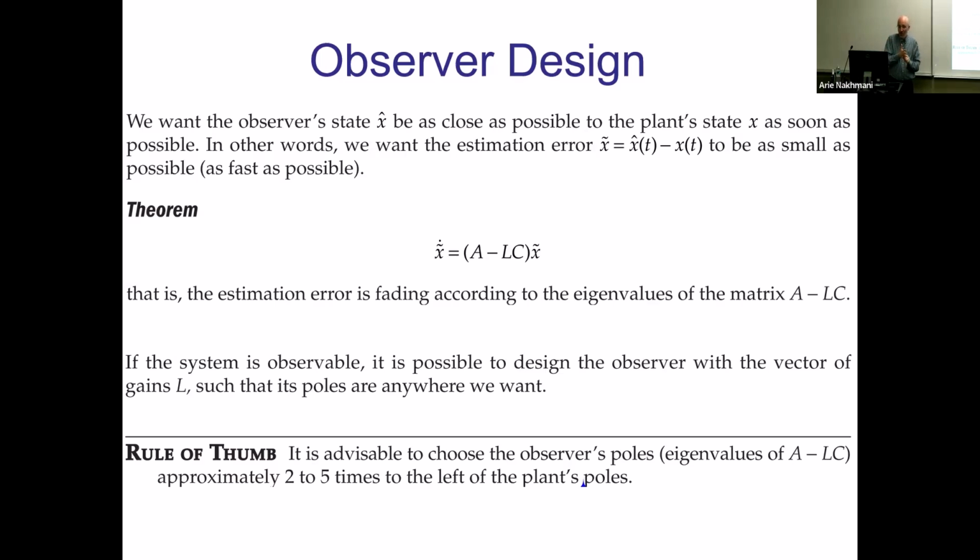Because on the input you decide, so you know it precisely, typically. This is much better tolerance. But y is what you measure with the sensor from your system, right? So it could be not very exact, yes. So if your sensor was perfect, in principle it would be best to have the shortest possible. Right. And this is what Kalman filter will actually do.